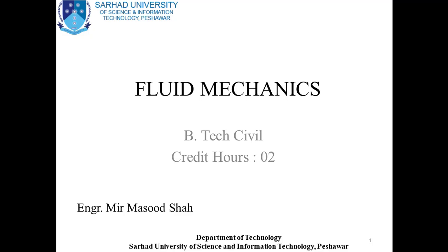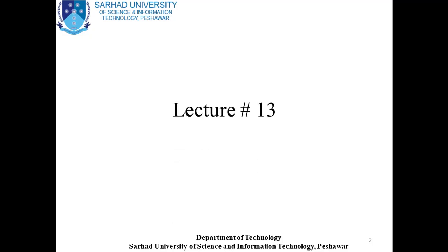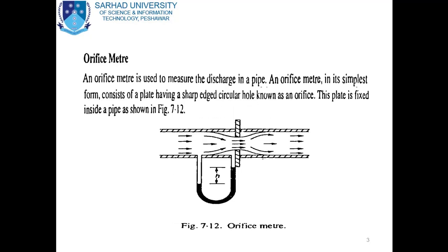As I am teaching you the subject Fluid Mechanics, today is your lecture number 13. In lecture number 13, we will study about Orifice Meter, which is one of the applications of Bernoulli's equation. So an orifice meter is used to measure the discharge in a pipe.